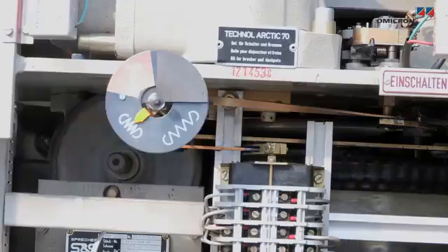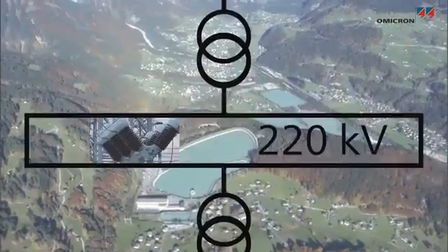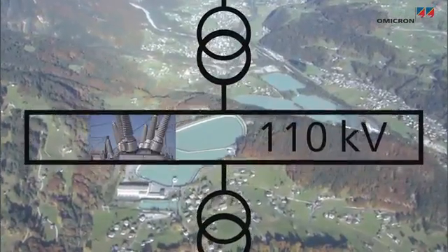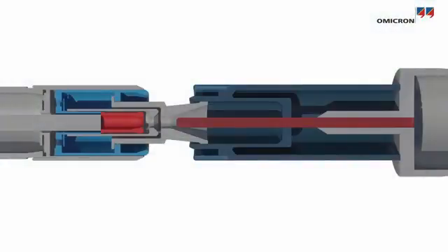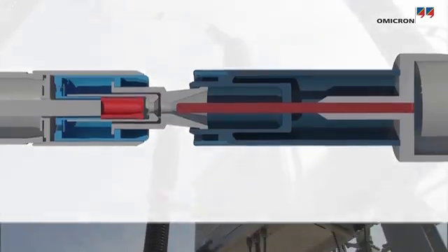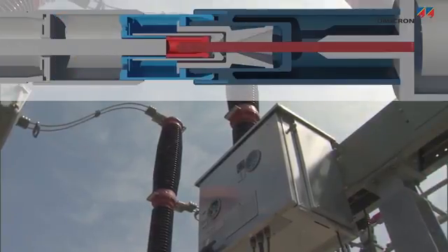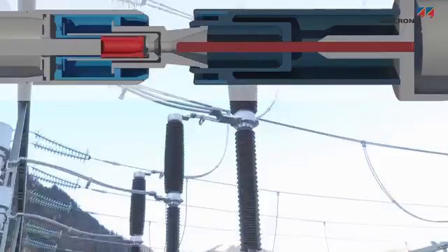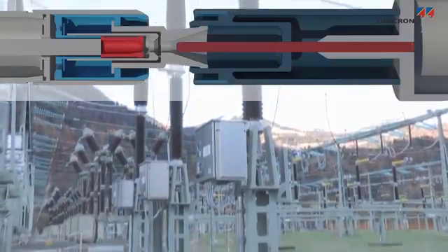Circuit breakers allow the flow of energy to be controlled by safely switching currents on and off at all voltage levels of the energy grid. In the open position, they have to ensure isolation across the switching distance, between phases, and to ground. In the closed position, they have to allow the energy to flow with minimum losses. They need to be able to reliably interrupt short circuit currents without damaging themselves or adjacent equipment, even after long idling times.